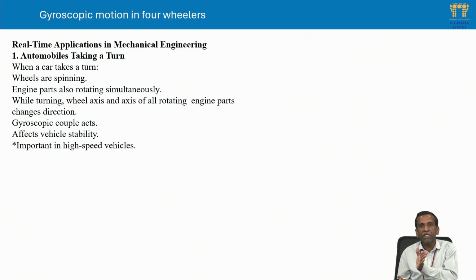When the automobile is taking a turn about another perpendicular axis, it is being rotated, that means precession. Because of this precessional torque, or angular motion, which leads to an input torque, the entire automobile is going to rotate about the third perpendicular axis. That is called gyroscopic action.